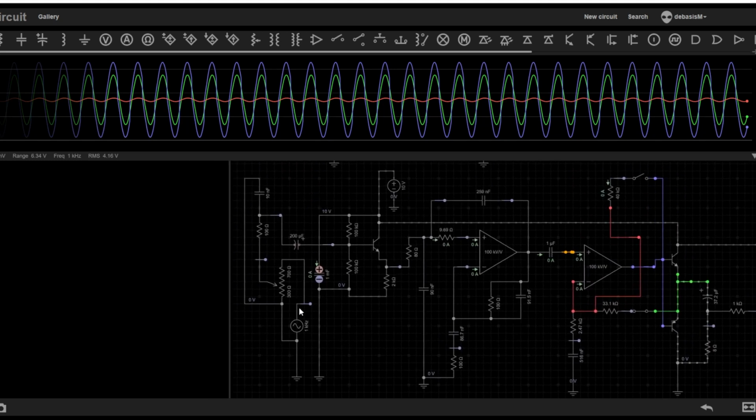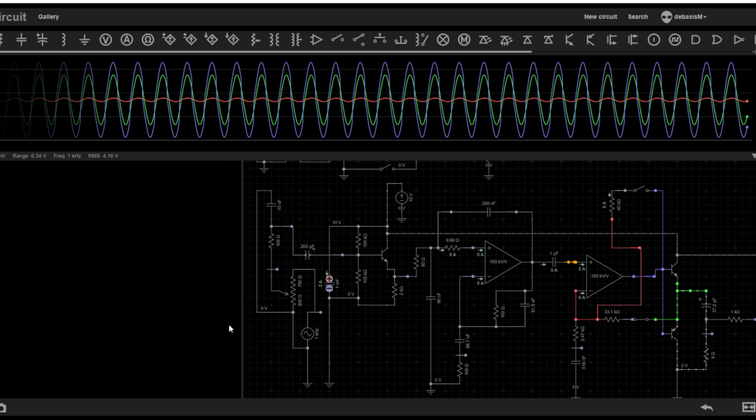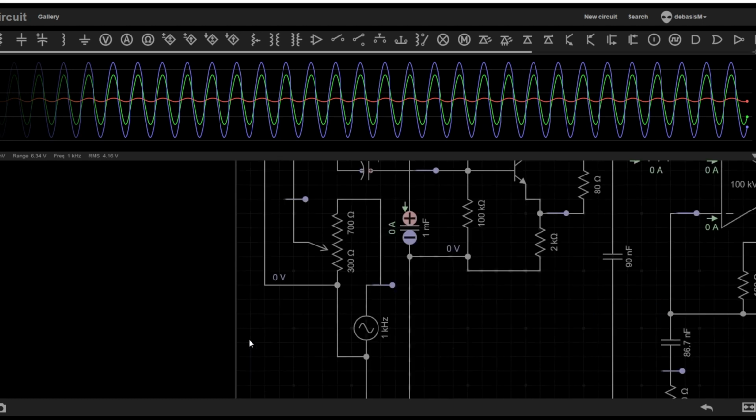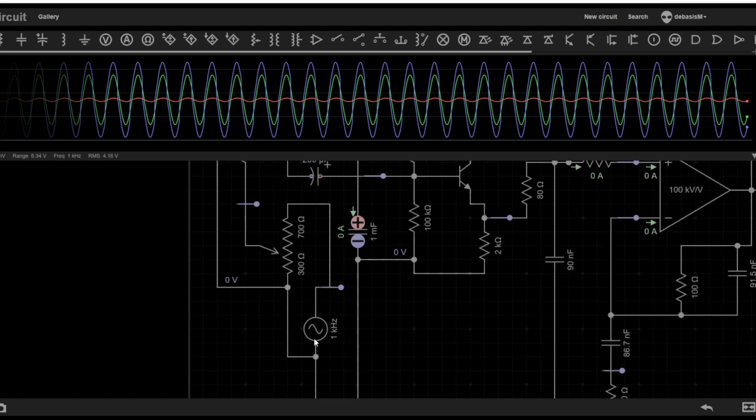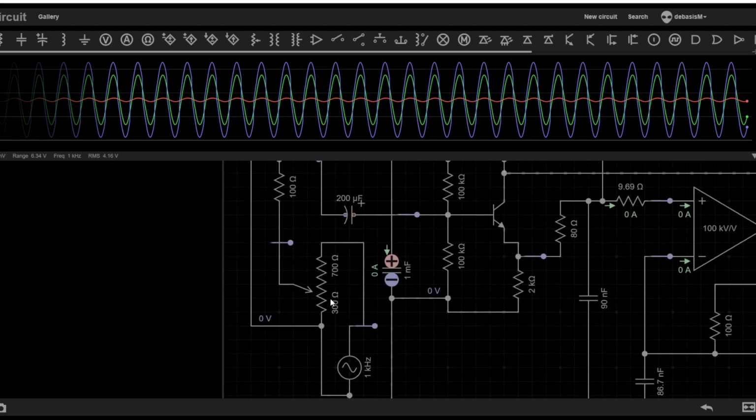We all know the audio signal in the audio system enters the system through the 3.5 millimeter audio pin. Now the question is, what happens after that? Let's say this oscillatory signal source is the signal that is coming from some computer or maybe a mobile phone and is entering the audio system. Now it directly goes to the volume controller, which does nothing but vary the voltage. That volume controller is a potentiometer, where you can adjust the effective voltage by changing the resistance. Okay, so that's what a potentiometer does.